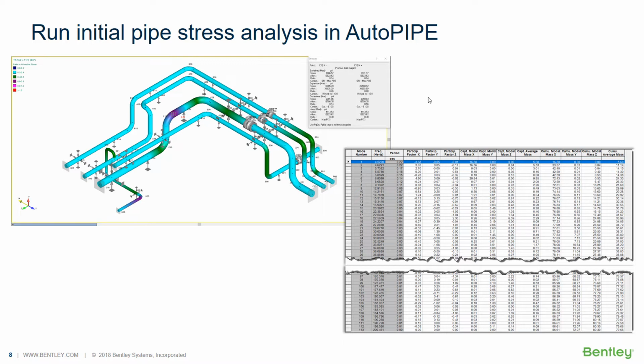On the lower right side, what I'm showing here is I also ran a modal analysis, because what you're going to see change in your piping model when you connect your piping and structure is the flexibility of the model. And when we talk about flexibility of a model, we're basically talking about our modal analysis, our natural frequencies that we're going to be able to extract from that piping model. They depend on the flexibility of the piping model, or the rigidity of the piping model.